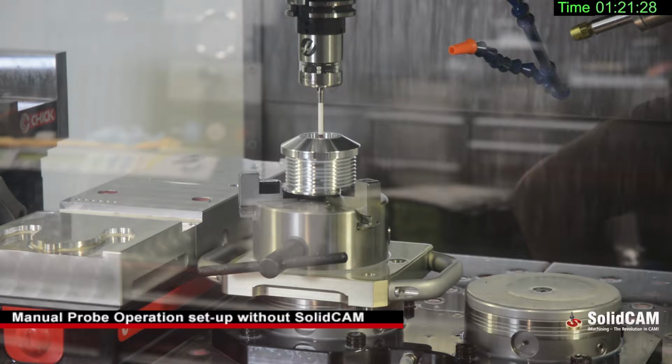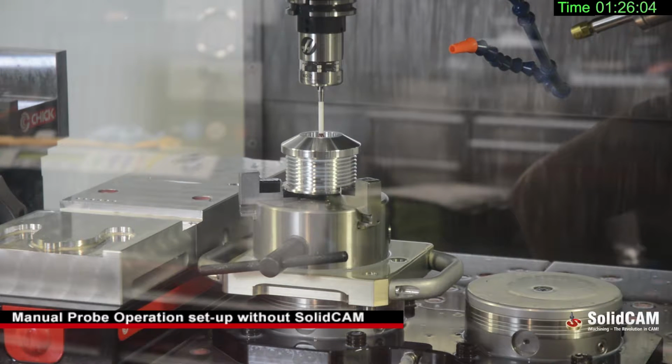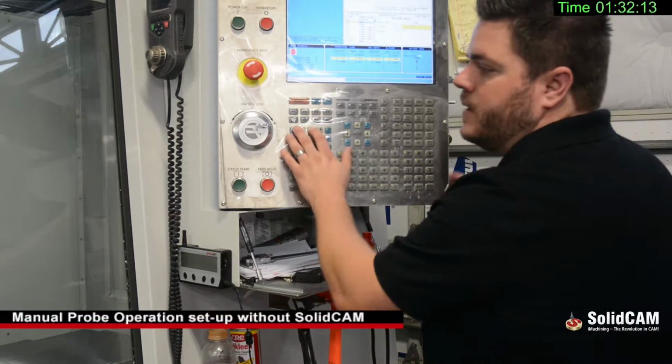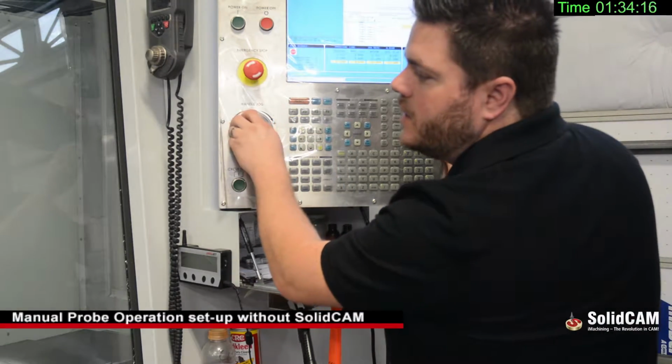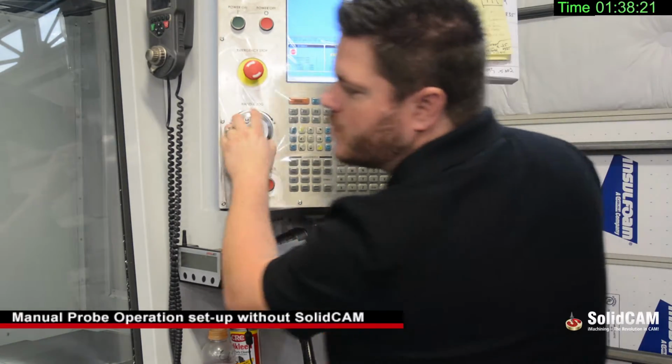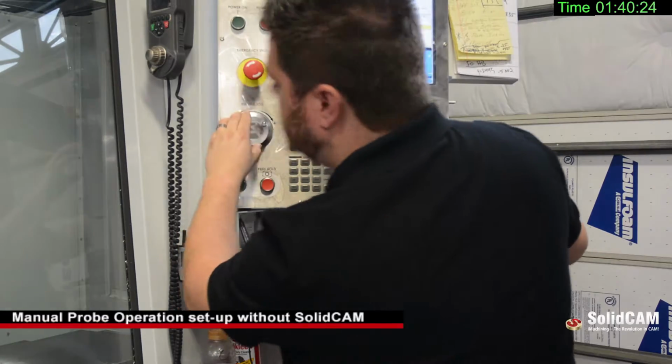And that final beep indicates that the data is saved into G54 for X and Y. Now all we have left to do is to find the Z. Now we're going to move our probe out of the pocket and over onto right above the top plane of the part.